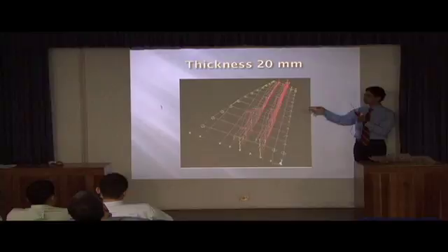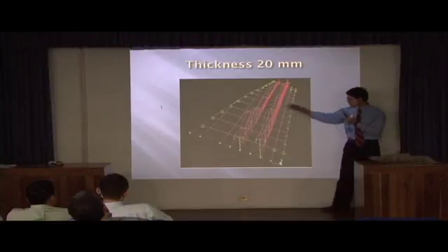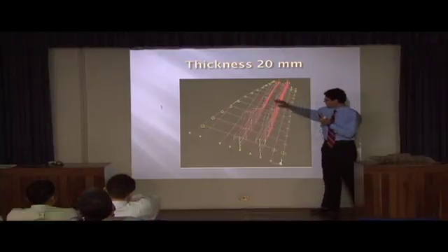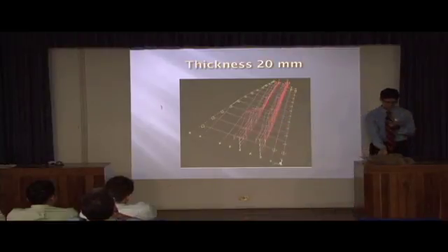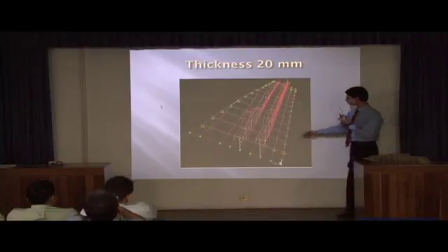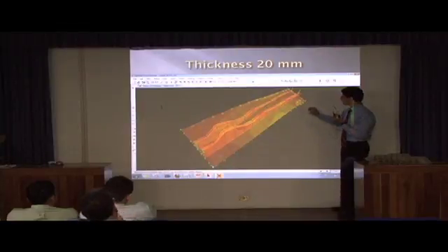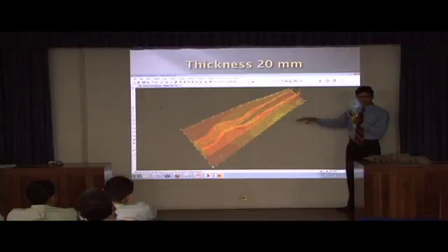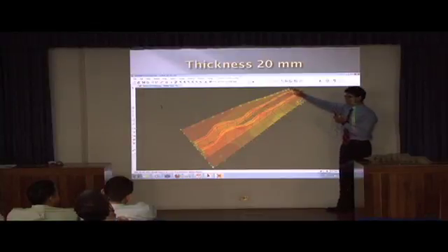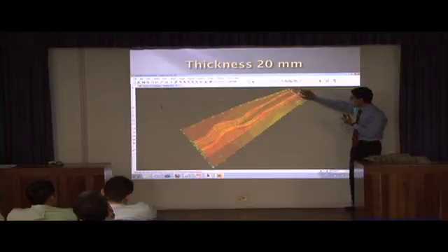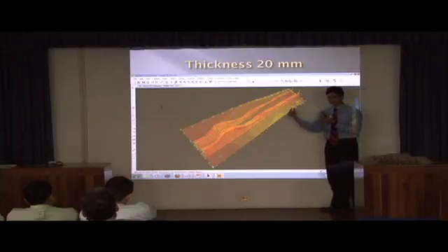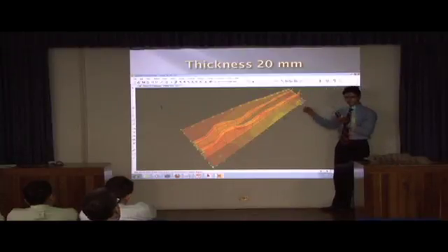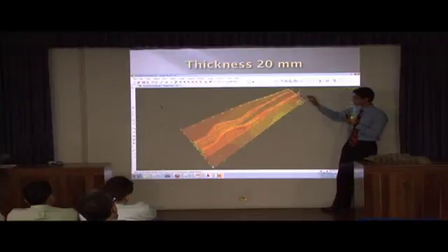Now we have to do the same procedure with 2 centimeters of thickness in the foundations. We could check that the two foundations try to separate, apart from trying to bend the whole structure. The concentration of stress compared to the previous presentations is practically the same, on the same group of joints. The stresses are higher than before because we have less thickness, but we can see later in the analysis that these stresses are not too high, so this structure works very well.